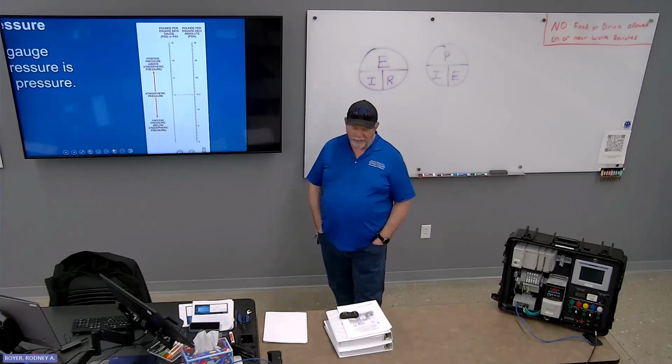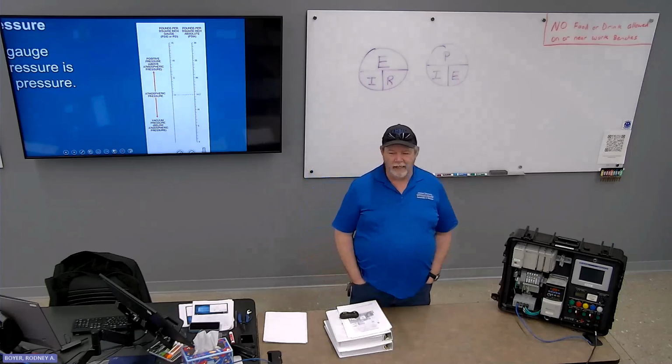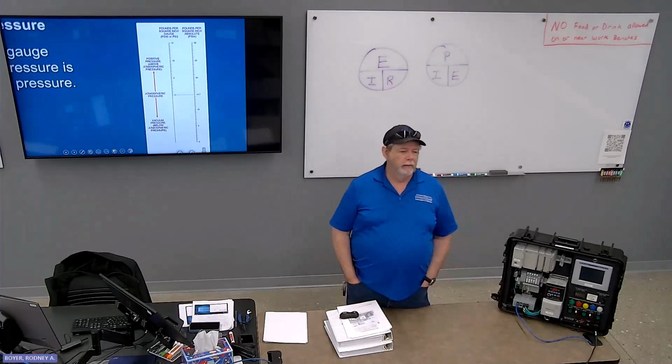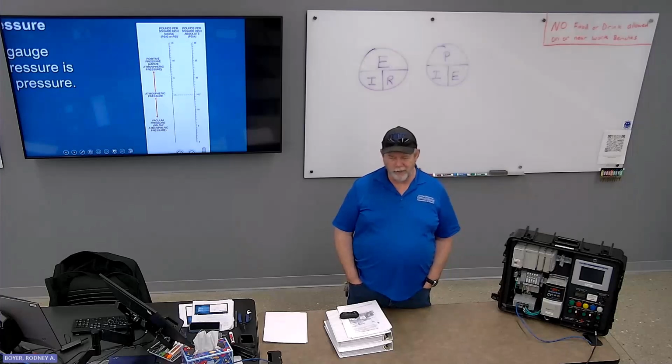When we are talking about PSI, unless we specifically say PSIA, we're going to assume PSIG. These gauges are set for gauge pressure rather than absolute. Also, anything above 14.7 psi A is pressure. Anything below 14.7 psi A is vacuum.